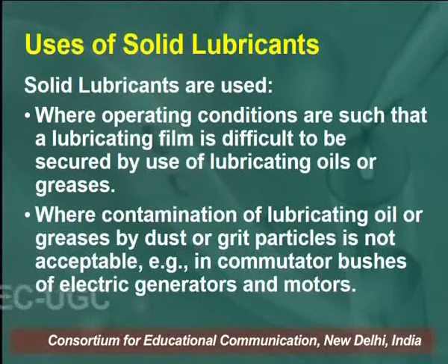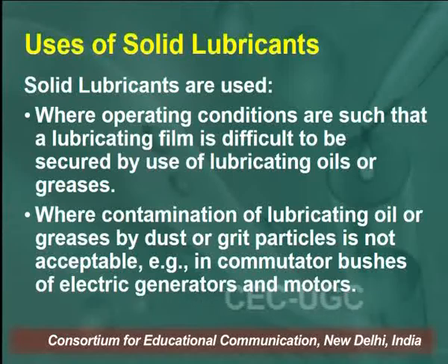Solid lubricants are used where operating conditions are such that a lubricating film is difficult to secure by use of lubricating oils or greases. It is used where contamination of lubricating oil or greases by dust or grit particles is not acceptable, for example, in the commutator brushes of electric generators and motors.